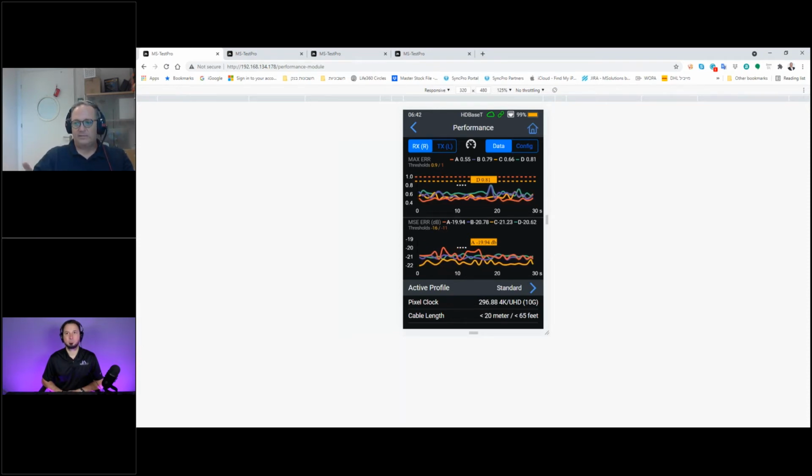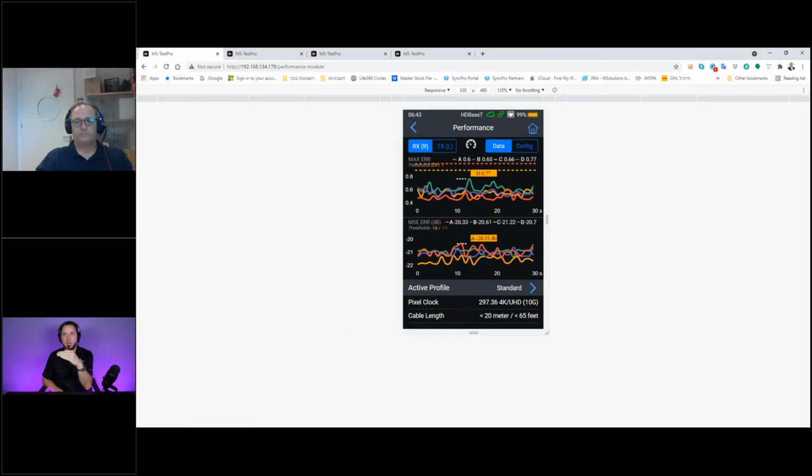So this actually tells you how far you are from a failure location in recovering the signal. Okay, and this is what you're seeing here with the thresholds. The lower that you will be, the better you have in terms of quality. It looks like on the top one, we're well under the orange line, and red, of course, is failure. Orange is it's good, but be cautious, maybe re-terminate. But when you're under orange, you're good to go.